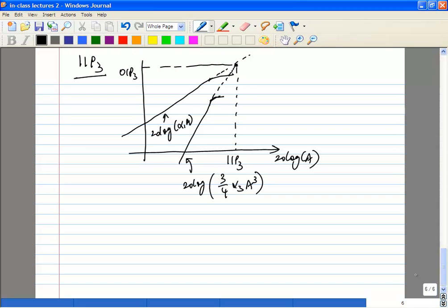So what you're going to do is vary the input amplitude, and if you plot the first harmonic fundamental, it will be a straight line at low powers, because at low powers your nonlinear effects don't come into play. Similarly at low powers, you know that the term 3/4 alpha 3 a cubed has a slope of 3. Now in a real case, you would actually compress a lot before you reach your IIP3.